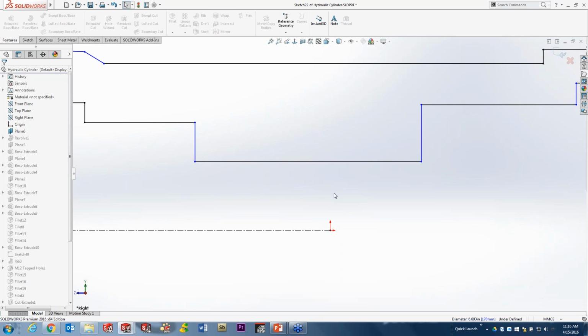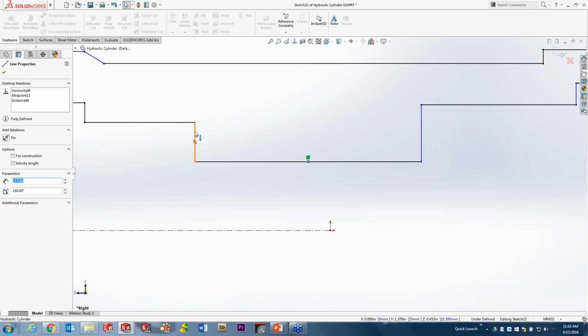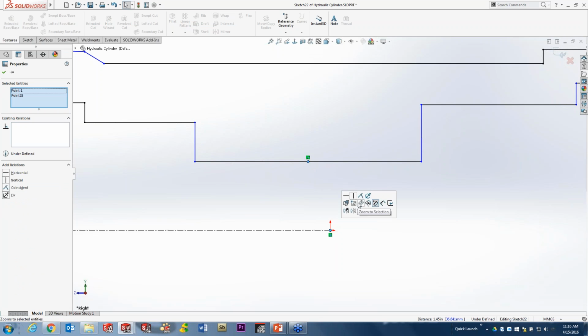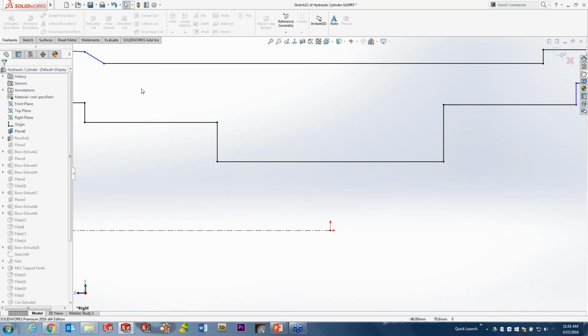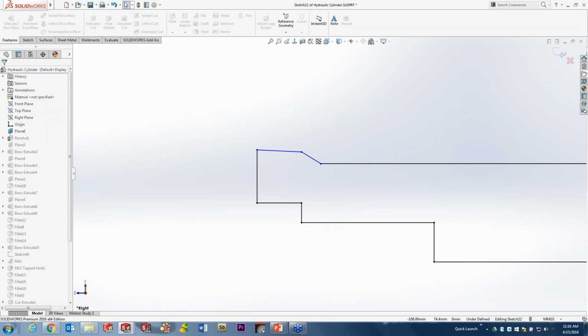Down here in the bottom, I want to access a midpoint to an entity. Now this used to take a right click to grab it. Well, now when you hover over the entities, it's really just a regular click. When you hover over something, it dynamically imprints, it highlights, and allows you to simply pick and select that. So I can easily select a midpoint with a single click, another point with another click and a control key, and we'll just go ahead and make those vertical to each other. So very quick access to midpoints on any entity.